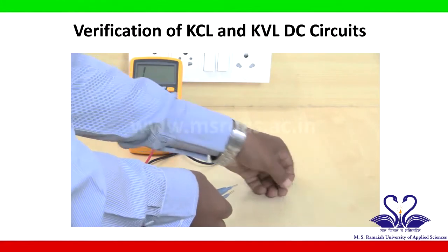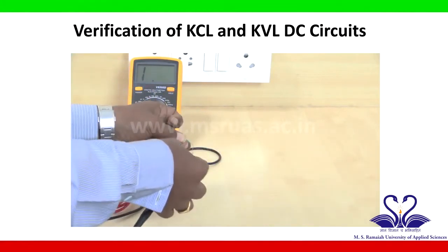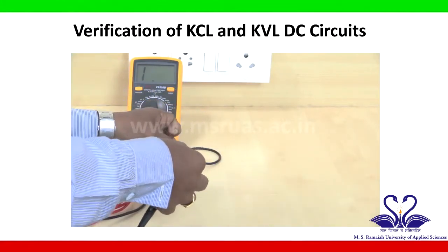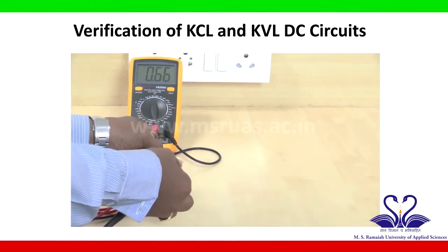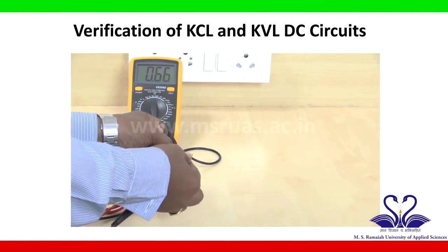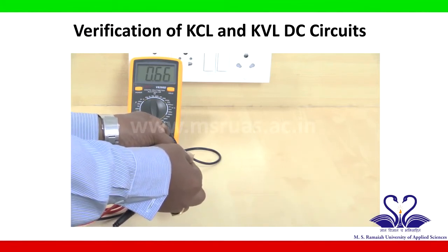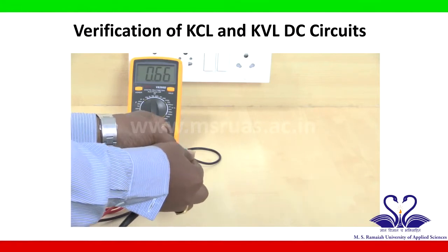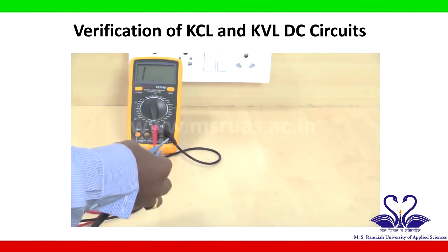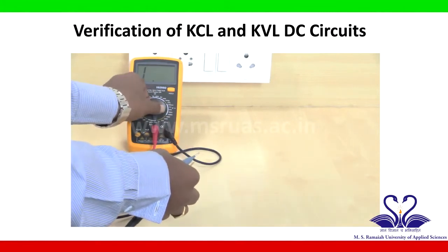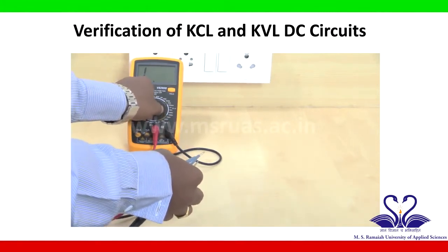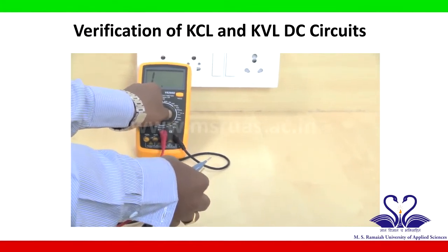Next, the final resistor is showing 0.66 kilo ohms, so that is approximately equal to 680 ohms. So this is R5. And make sure that you keep the multimeter knob in the resistance position to measure the resistor values.